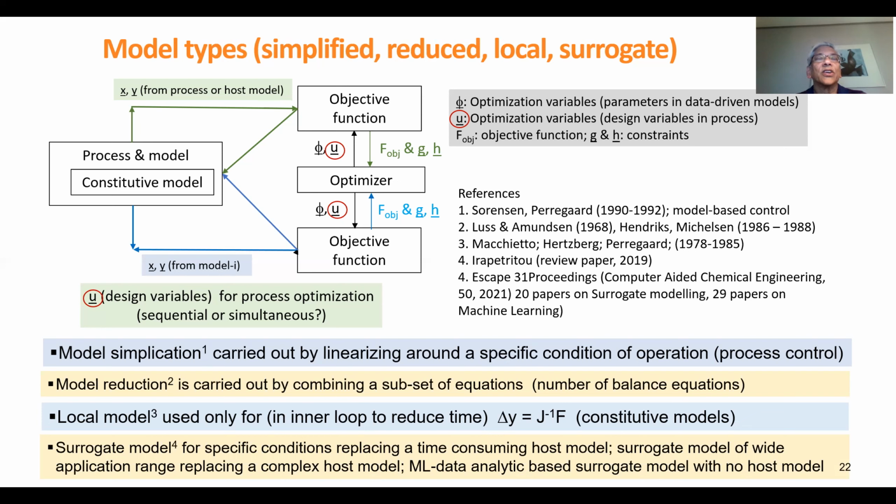The surrogate model is developed so that it can represent the host model within the conditions that they have defined. I'm not sure if that is possible for the thermodynamic models unless the derivatives have been taken also, and the thermodynamic consistency tests have been done. Otherwise, it would be quite dangerous to take only the property values and create a surrogate model.